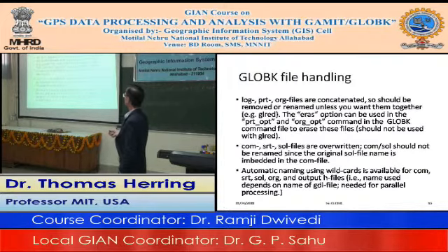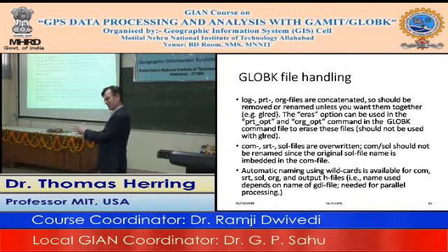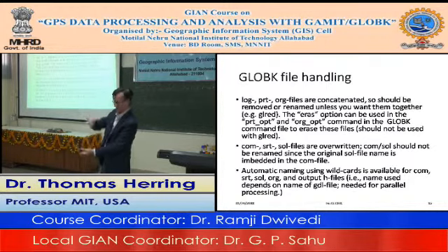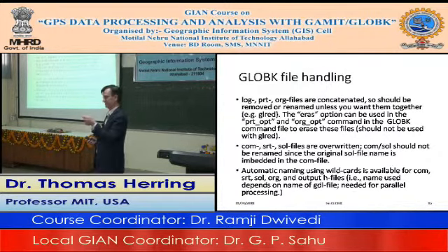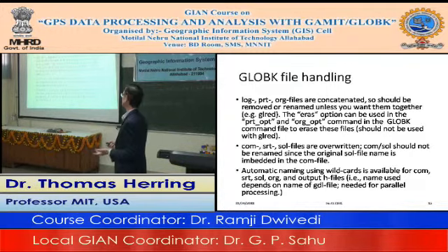So then file handling: the log files and prints by default are actually concatenated together. So when you run GLOBK, if you keep the print file name or this org file name the same, the next solution gets written at the end of that one. That sometimes is a confusion when people change something and then they go and look at the solution and realize it doesn't look like it's different. But if they look down, they'll actually see there's a second solution below it. That's very important when you run GLRED, because what you want to do is generate a time series. So each of those individual runs, you want them typically to concatenate into the one file. And so that's why it's done that way.